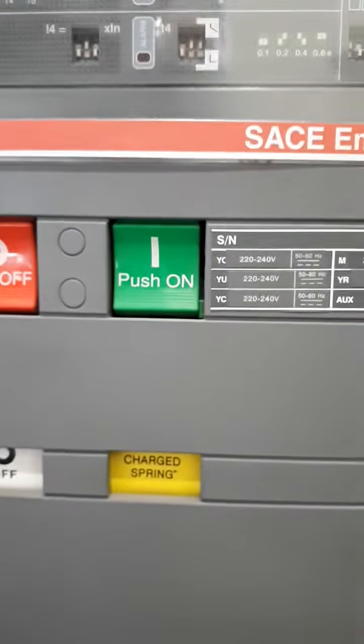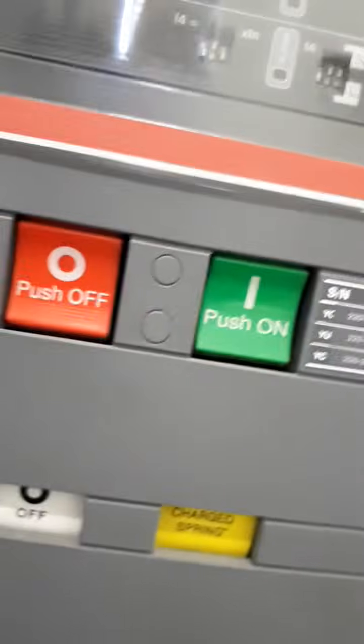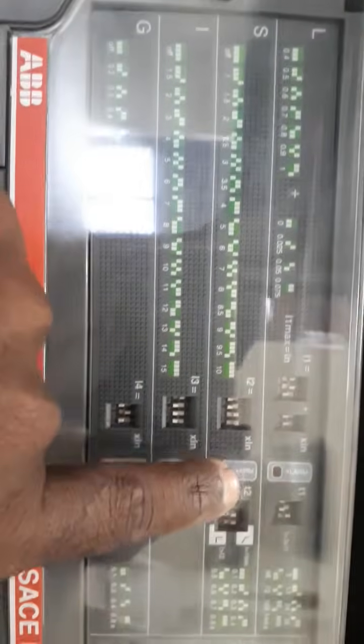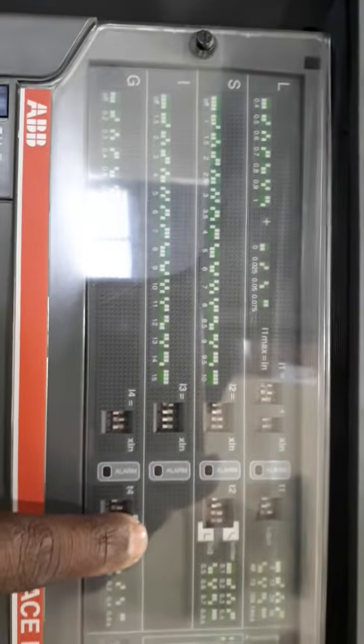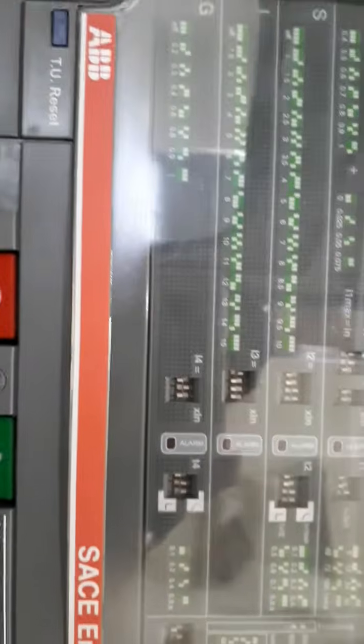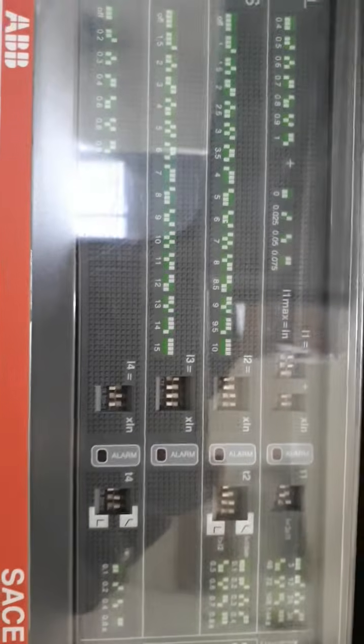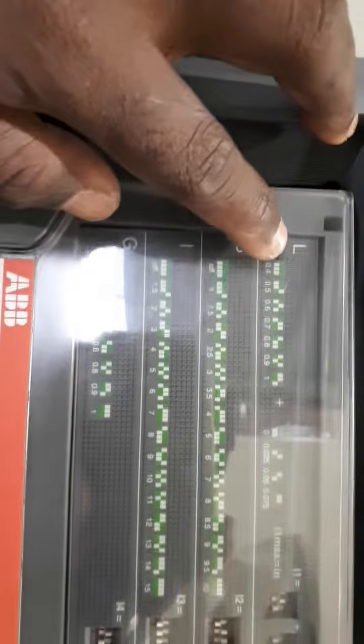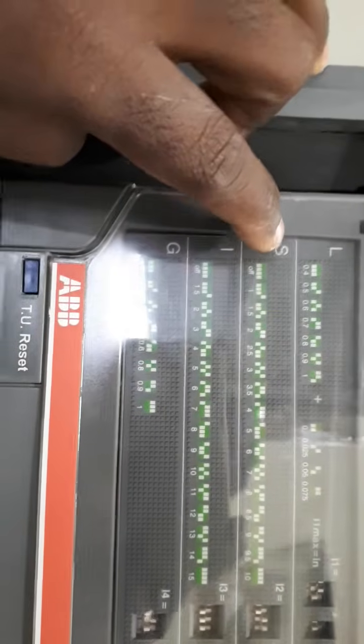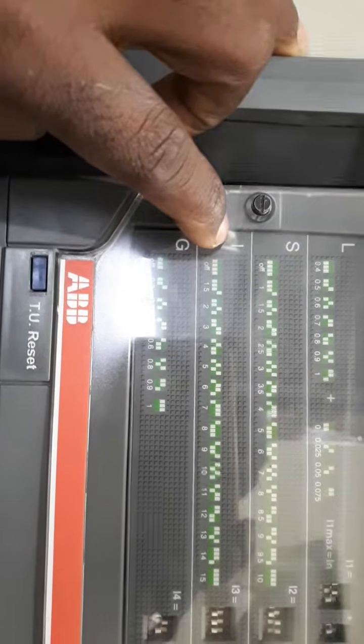Now I am going to tell you about the importance of trip setting value. Okay, this is the relay setting coordination. So here we have the settings. This one for current limit setting, this one time setting, because all trippings follow the time current curve. Okay, only the current and time curve is followed by all trip settings. So first one is overload, this one short circuit, instantaneous, ground.